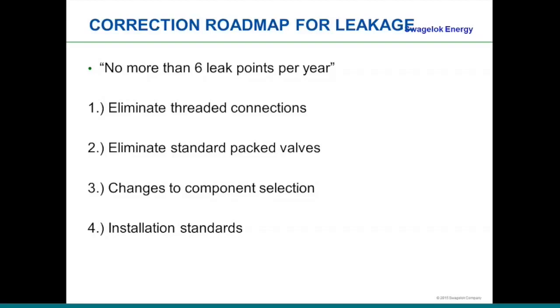A roadmap for leakage: no more than 6 leak points per year. Eliminate thread connections. Eliminate standard packed valves. Change the component selections, selecting components that are not prone to leaks, like packed valves, larger valves, going to different types of valves, butterfly, ball valves.